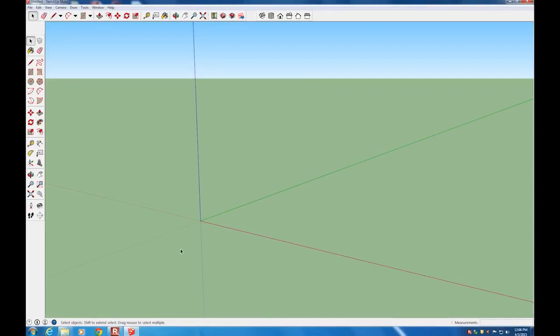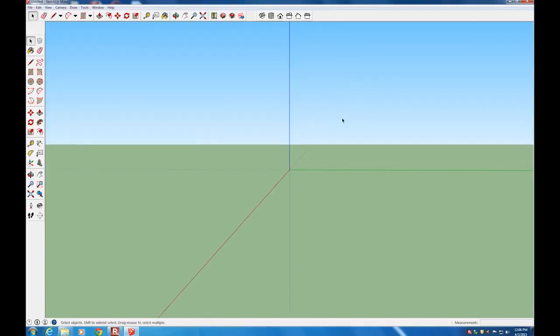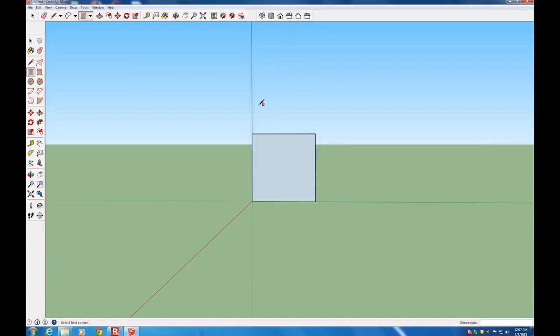So we're going to start drawing the chair. So to start, we're going to go to the right view. So go up to the Center Views toolbar, click on Right, and that gets us close to the orthogonal plane that we want to be in for drawing from the side. And then I click on the Rectangle tool. Come back over to the center of the screen, click on the origin. You notice the little yellow inference point appears, and then click and start dragging out the direction you want your rectangle to go, and then type the dimensions. In this case, 0.5 meters by 0.5 meters. So I type in 0.5, 0.5, click Enter, and the rectangle is created. We can zoom in for a closer look on that.